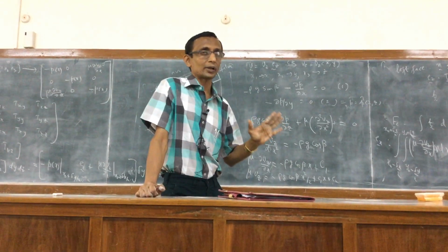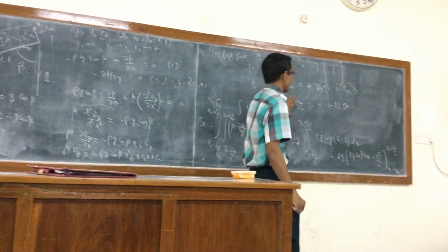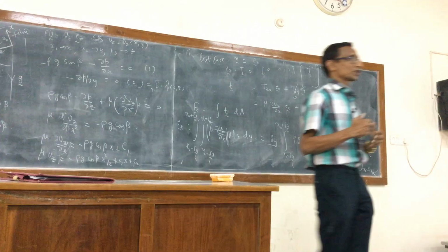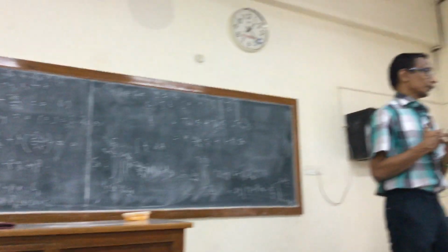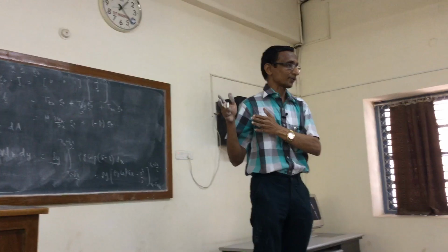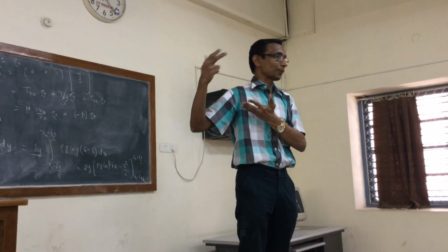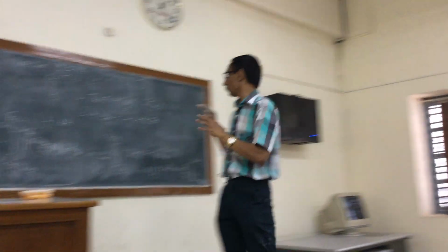The integration typically will be only over x, because in all the cases, the integrands, whether it be p or the shear stress component, are functions only of x. So wherever there is a variation in x, so this would be the left and right faces, and the front and back faces, each one has to be done independently.